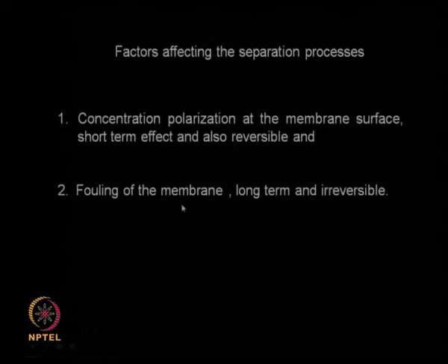Now this is a long term process, this is irreversible. Concentration polarization, I see at least, is reversible. I can stop the process and do some cleaning, and then again I start my membrane process, Cs will be equal to Cb. So it is a reversible process, it is a very short term effect, whereas the fouling is a long term effect and it is irreversible.